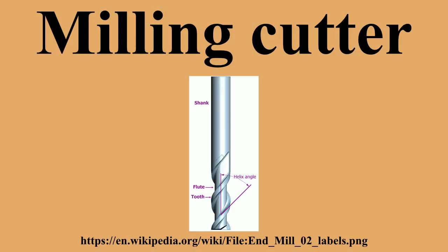Spindle speed. This is the rotation speed of the tool, and is measured in revolutions per minute. Typical values are from hundreds of RPM up to tens of thousands of RPM. Diameter of the tool. Number of teeth. Feed per tooth. This is the distance the material is fed into the cutter as each tooth rotates.